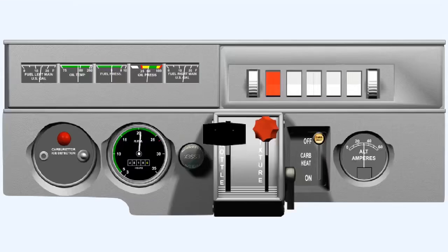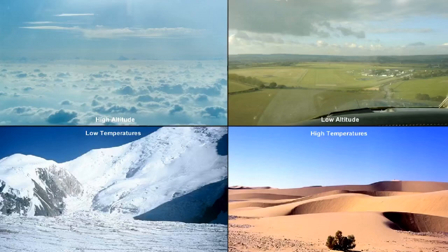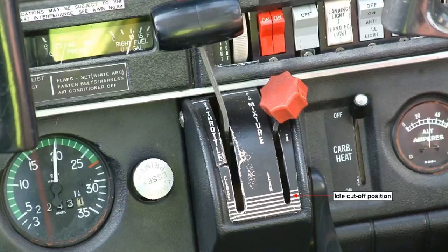The carburation system must first of all control the air-fuel ratio in response to throttle setting at all selected power outputs from slow running to full throttle and during acceleration and deceleration. The carburation system must also function at all altitudes and temperatures within its operating range. Finally, the carburation system must provide for ease of starting and generally incorporates a means of shutting off the fuel to stop the engine.